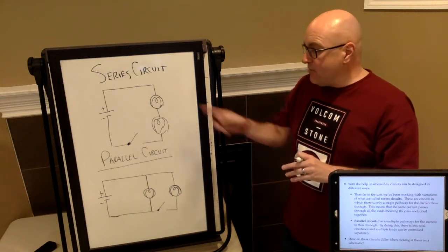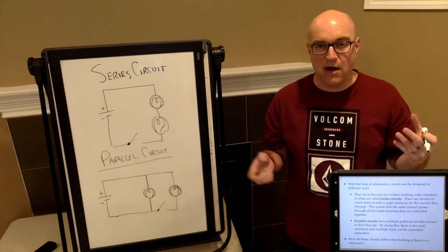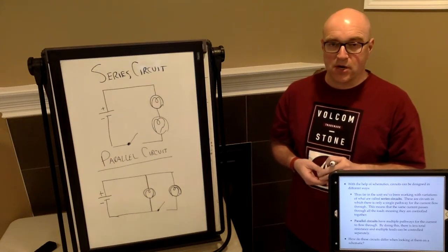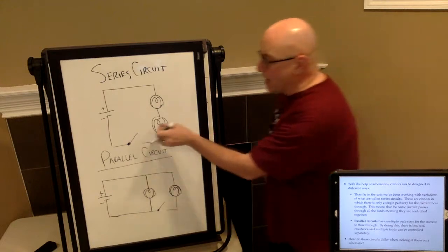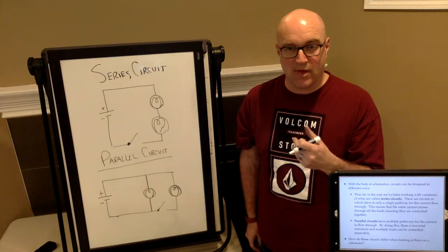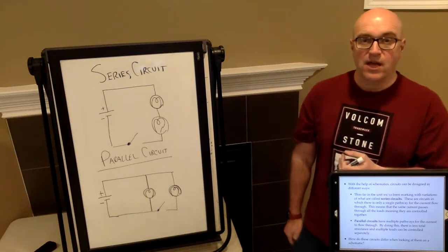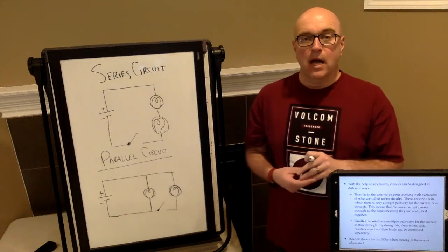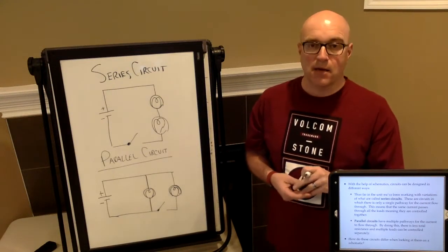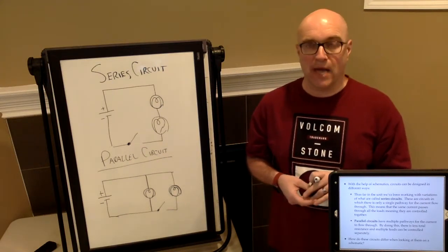An example of that would be Christmas lights, where when one light bulb goes out in the strand, all the lights die. That's essentially a series circuit. If there's one break in the line of the circuit somewhere, one place where the electrons can't flow through, all of the items on that circuit shut off. That would be a real problem in your homes. For example, let's say I have a bunch of pot lights in my house, like I have here in my basement. I've got a bunch of pot lights that are lighting me right now.